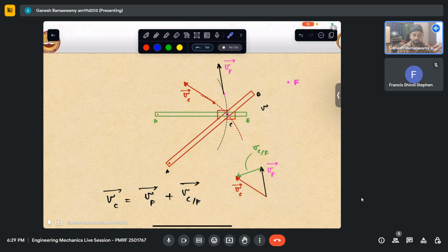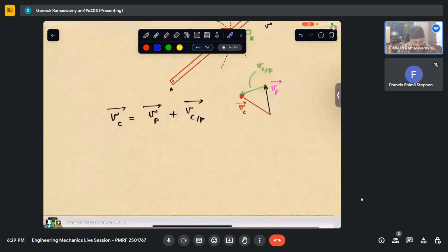Slotted member or a collar, howsoever it is. So it is actually pointing towards D invariably. So it is parallel to that slot. And the other one, I can see it is perpendicular to that slot. So if I know this vector and it is rotating with some omega, this omega cross this F will give me Vf. So that is what we essentially are doing.